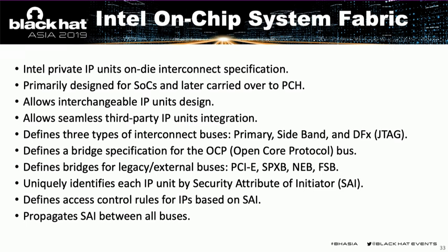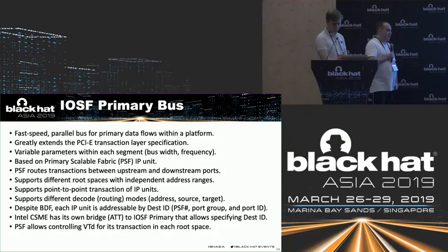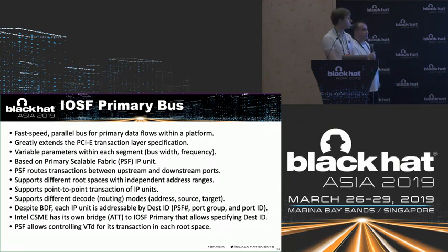We also have found that each device in the IOSF hierarchy has a special unique identifier, named security attribute of initiator, or SAI. Using the SAI, all access control inside IOSF is performed. IOSF primary is developed for high speed primary communications or primary data flows.